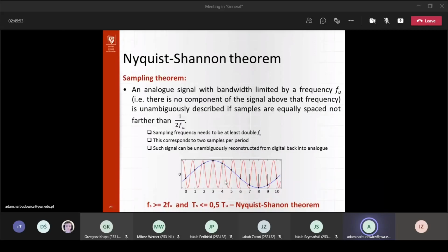In that case, you would take your signal, convert it from the Wi-Fi frequency of 2.4 gigahertz to the baseband, which would be 20 megahertz, and then apply the sampling with the 40 megahertz Nyquist rate. That's how it would work. I'm not sure, is that what you were asking, or does that answer your question?